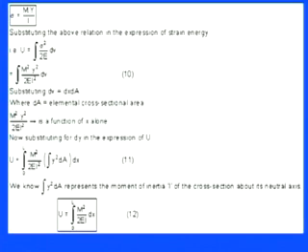So dA is the elemental cross-sectional area of that particular beam. Now what we have, M squared y squared divided by 2EI squared, is simply a function of x only. So you see, these are all constant terms. With that, we are simply manipulating those terms in the strain energy expression.